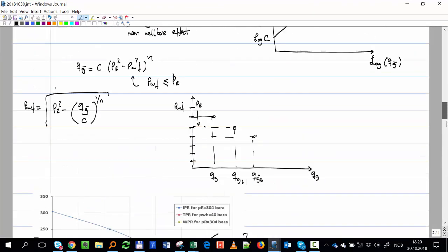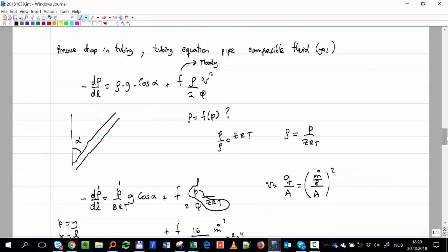We came from the Bernoulli equation for pipe, and one important thing we have neglected here is the acceleration change, the change in velocity in one section of the pipe. That is not 100% correct, but it's an approximation. The next thing we said, well, the equation has density, and we know density changes with pressure. So we have to put that in the equation somehow to eliminate the number of unknowns.